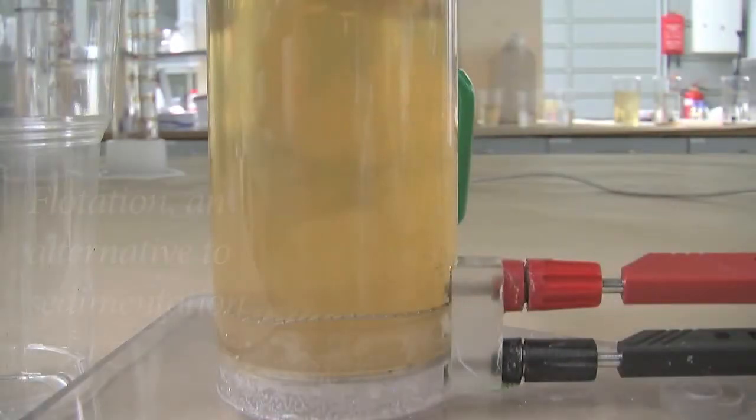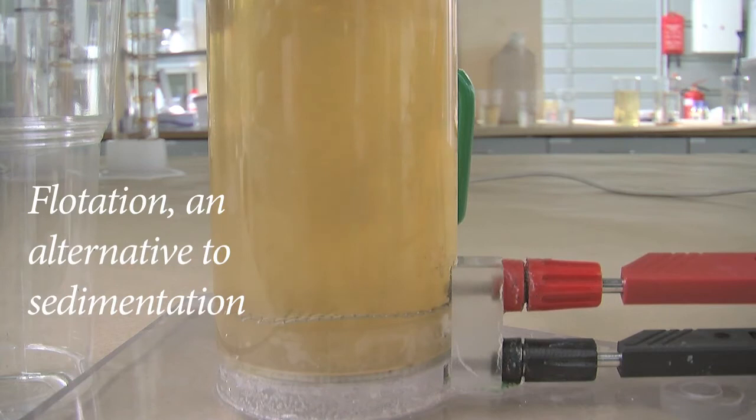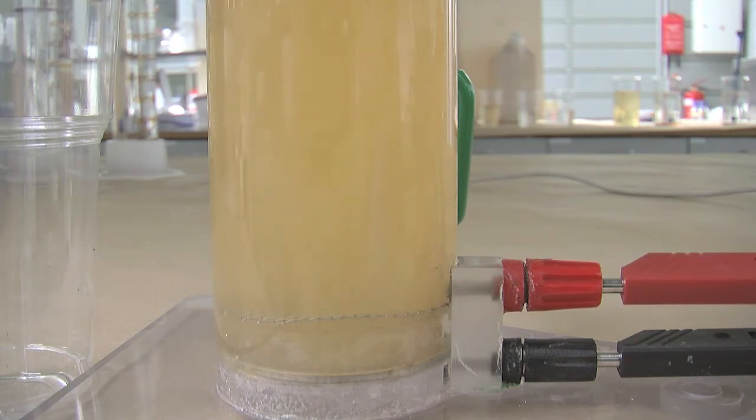As an alternative to sedimentation, clarification is often implemented by flotation. Flotation, in a sense, is the opposite of sedimentation. In flotation, the floc particles are induced to rise to the surface of the tank by entrapment of gas, usually air, within the mass of the floc. The resulting floc-bearing foam is skimmed off the surface of the flotation cell, and clear water is decanted from a lower level of the cell.